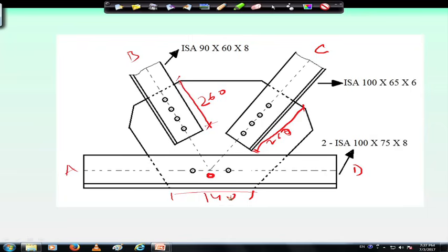So, in case of this, if we consider, in place of a 20 mm diameter bolt, a little higher diameter, then this length could be reduced. So, the length of the gusset plate in different directions can be reduced by increasing the bolt diameter, and if we increase the bolt diameter, the number of bolts will be reduced, and as a result we can find a lesser length of the gusset plate towards that member. So, this is how one can find out the gusset plate dimensions.